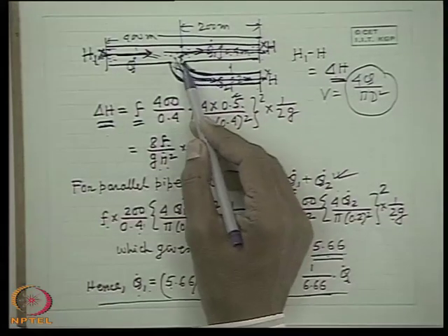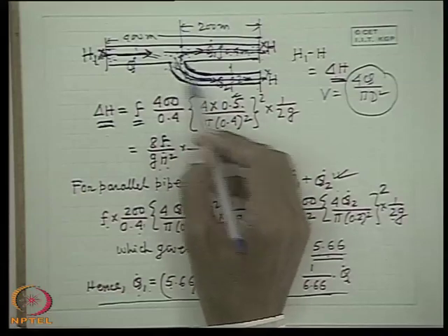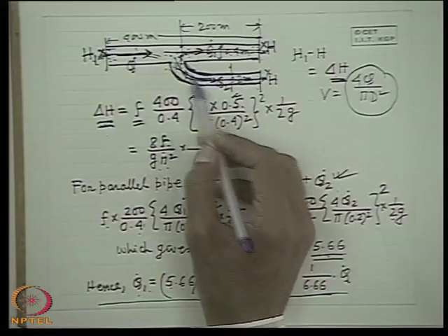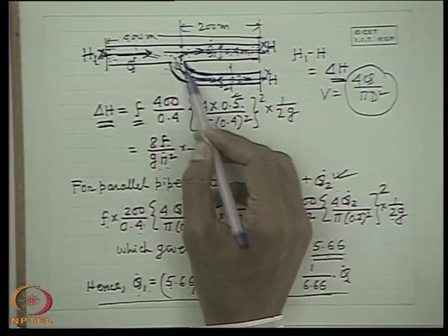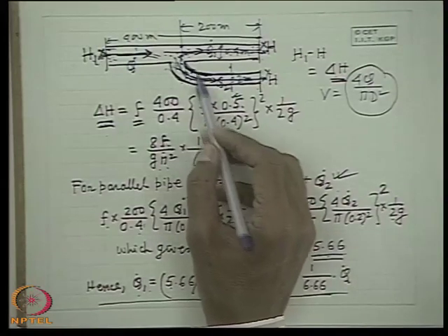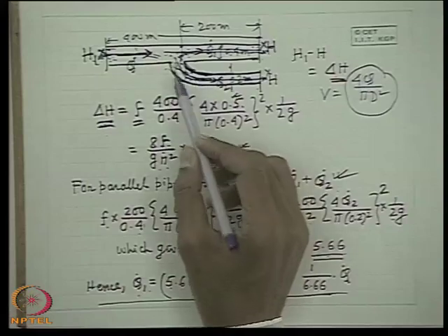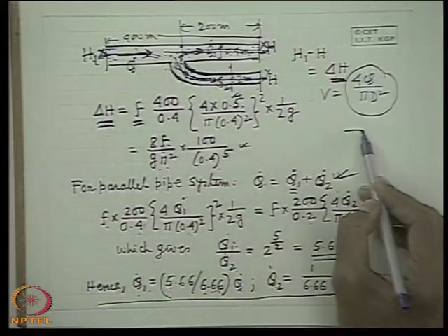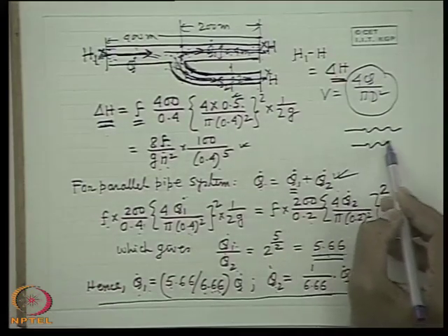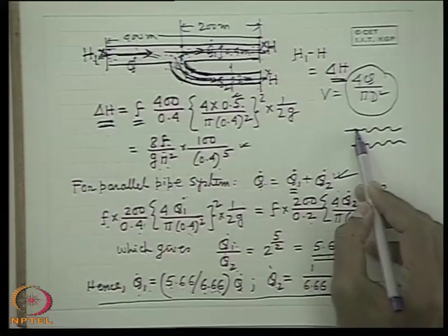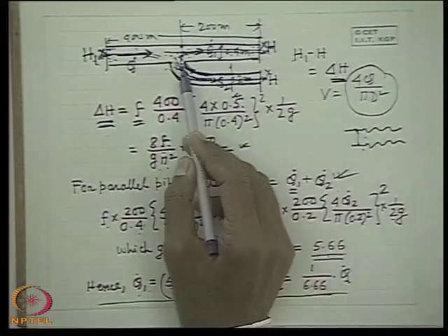In practical applications, you will know the pipe bend: what is the angle of the pipe bend, what is the diameter. Depending upon the diameter and the angle, the loss coefficients for the pipe bends are known, then you add it. Very correct. But here nothing is told, as if two parallel lines like that. So there are two parallel lines, these 2 points are the same. That means we neglect this bend.